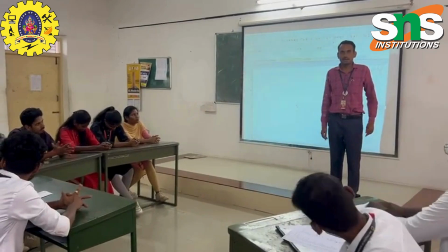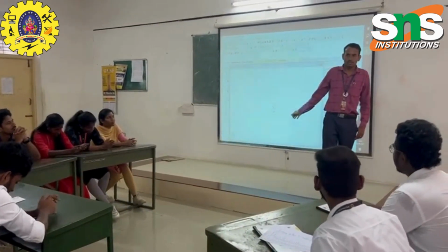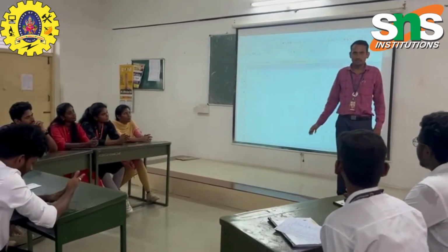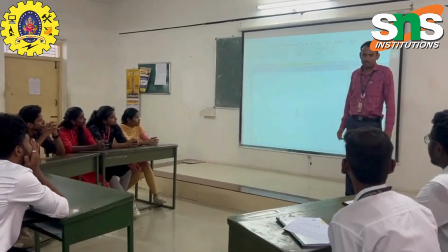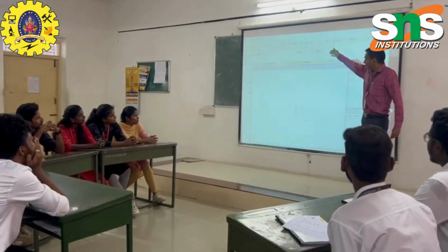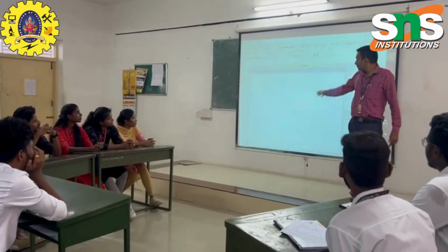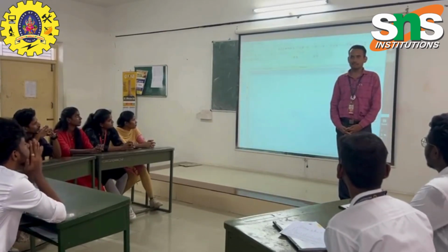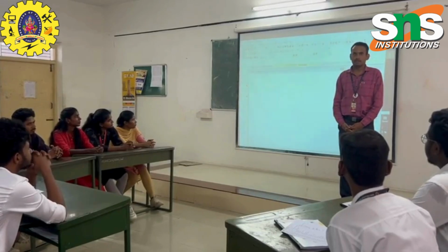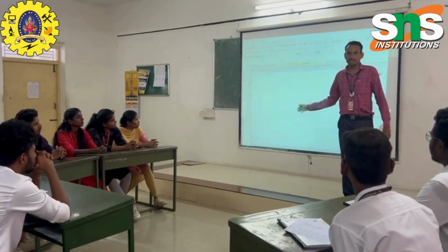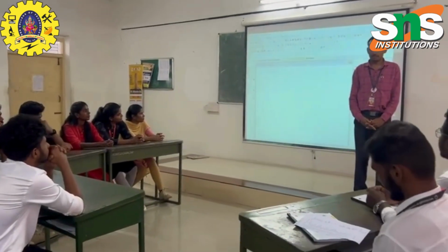Today's class, I am here to give hands-on training on the software STAAD.Pro. In this class, we are going to deal with calculation of shear force and bending moment using this STAAD.Pro software. You can see the interface of STAAD.Pro software, which is projected on the screen. So, in this class, our objective is to find out shear force and bending moment diagram for a cantilever beam using STAAD.Pro. So hope everyone knows about the basics of STAAD.Pro.